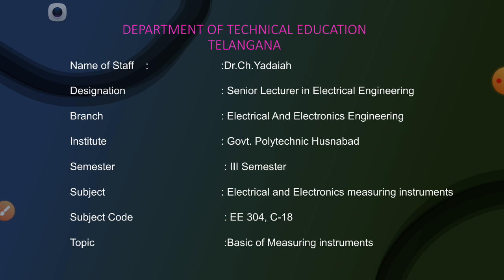In gravity control, a small adjustable weight is attached to the spindle, which provides the necessary continuous torque. The weight can be adjusted based on our requirement. Here the weight is due to the gravitational effect, which we take into consideration. What is the difference between the spring control and the gravity control?